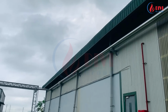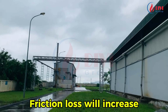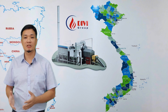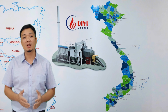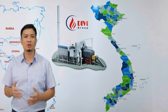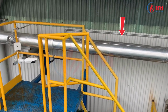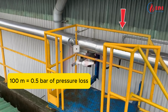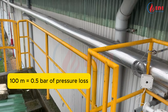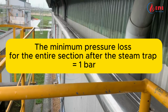If the pipeline has no natural slope, or if the pipeline is too long, friction loss will increase, making the total pipeline resistance much higher. Therefore, for the condensate to return to the boiler, the pressure after the steam trap must be high enough to overcome the total pipeline resistance from the trap to the boiler. For example, condensate from the steam trap must be lifted 5 meters to reach the main condensate line, equivalent to at least 0.5 bar pressure loss. The main pipeline is 100 meters long horizontally, assuming friction loss is around 0.5 bar, then the total minimum loss is 1 bar.